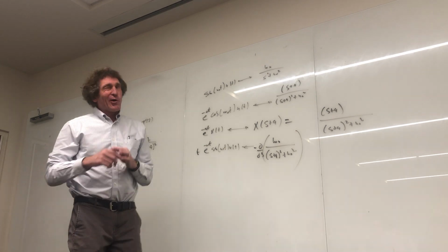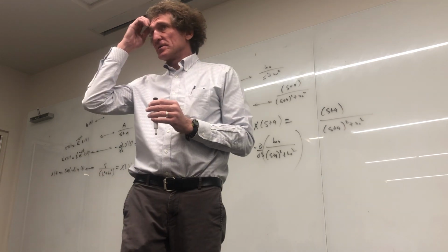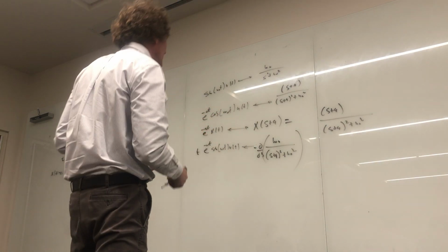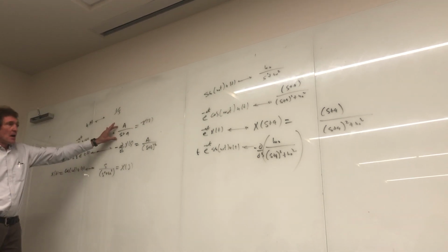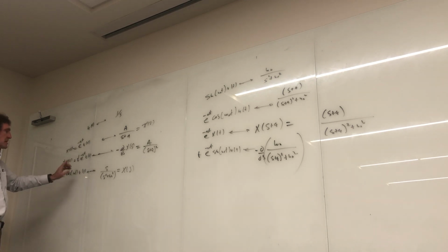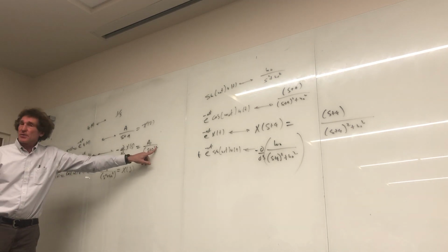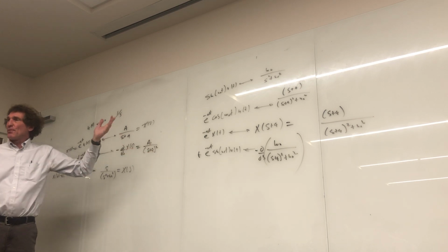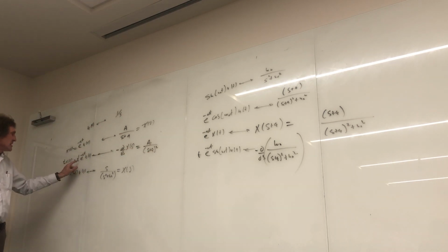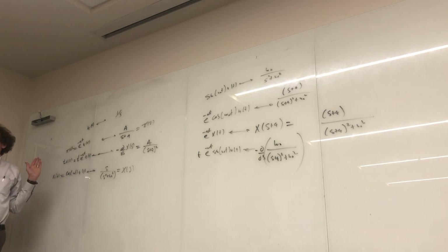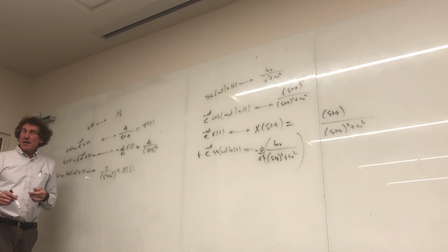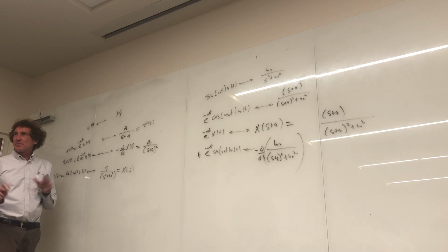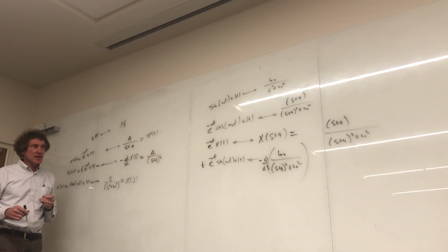Now, almost all of the partial fraction expansions will have the form of either a simple pole, a over s plus a, then a double pole like this. This is a double pole because it's to the power 2, right? It could be a triple pole, but a triple pole is just taking this function, t e to the minus a t, u of t, times t, and taking another derivative of that and throwing a minus sign. Follow me? Usually, third order poles you rarely see in this simple circuit analysis.